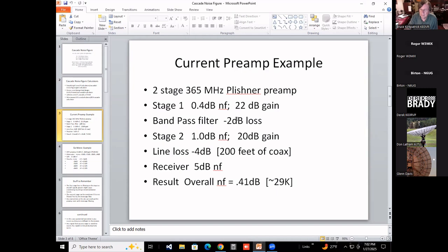And I want to make up the gain of this too, because that subtracts from this gain up here, and that's a little bit less gain than I'd like. I'd really like to see about 40 dB gain, typically, out of my preamps up there. Quite a few of the commercial ones have at least 30 dB gain, but on mine, I like to build in about 40 dB. And you're going to see the result of what I'm talking about in the next couple of slides.